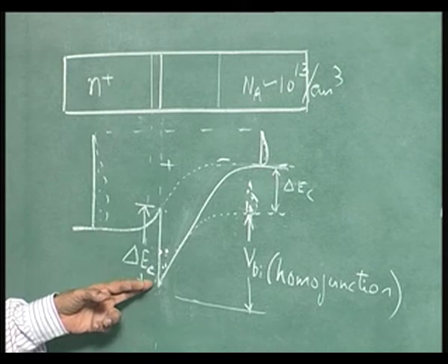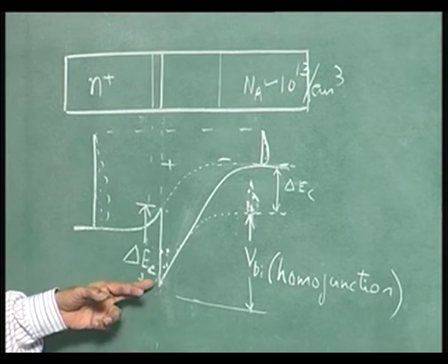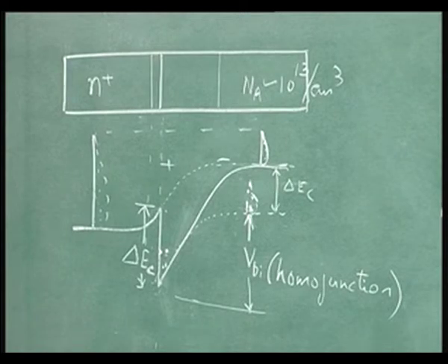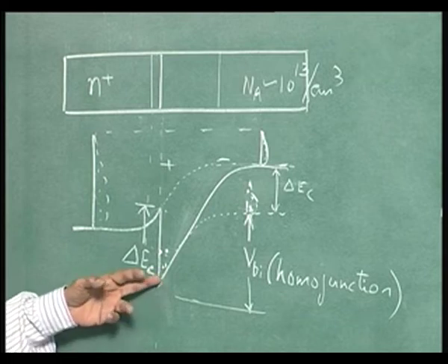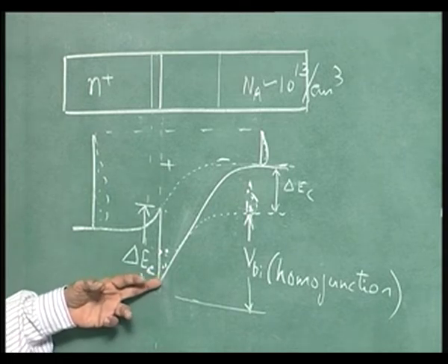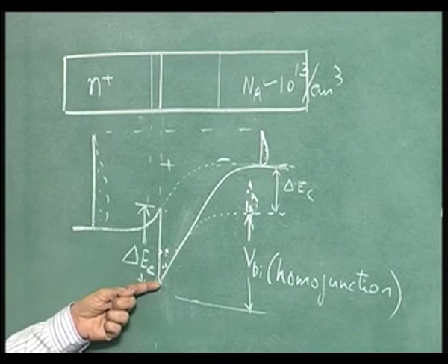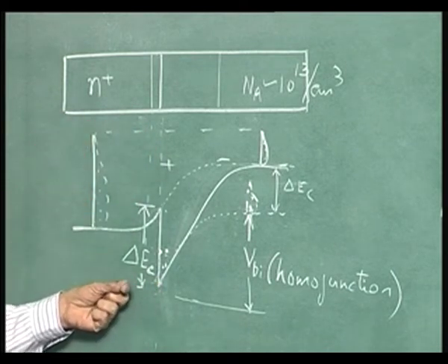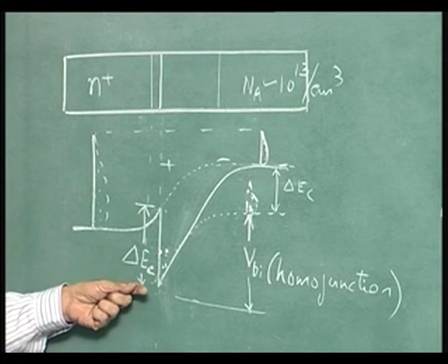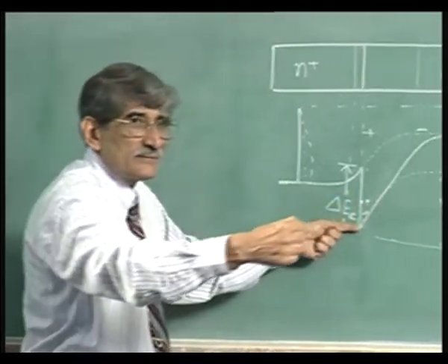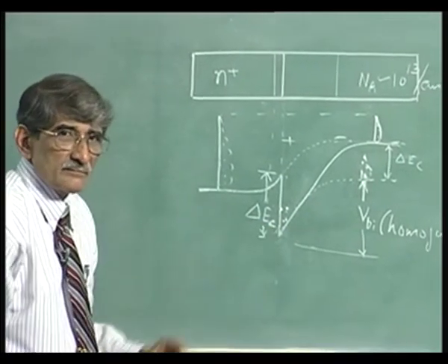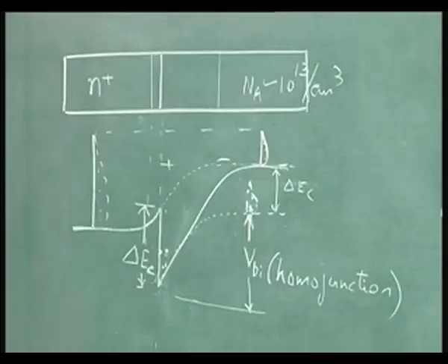Now, it is not enough if you have locked the electrons there, you must be able to use them. To use electrons which are locked up somewhere, you must be able to transport them. How do you transport them? You have got electrons which have high mobility, so put a contact here and a contact here. If this structure is going like this, put one contact between these 2 points. I apply voltage between the two, and electrons will be transported like that. If I have source here and drain here, I can transport that. That is what is done here.